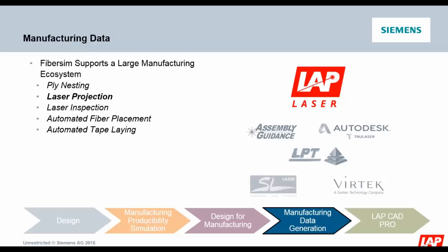processes. We have customers that are using things like fiber placement that end up stopping the machine because there are limitations to the tool, and they use laser projection to ensure that someone's laying tows in the proper area on that particular layer of material that's being put down.